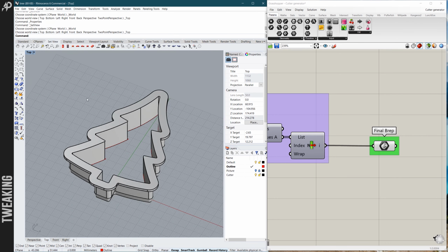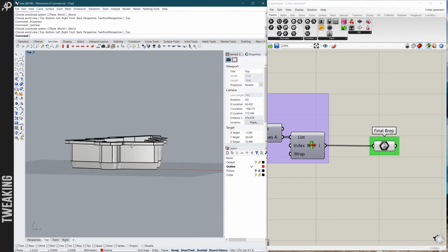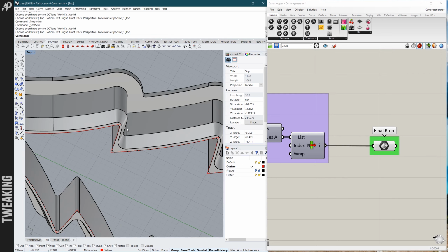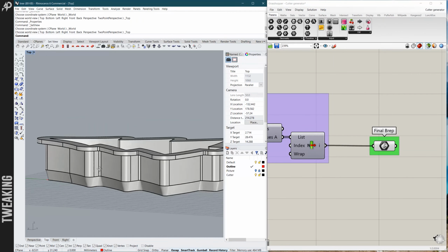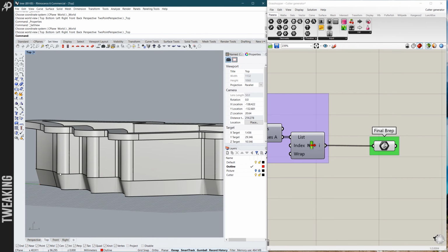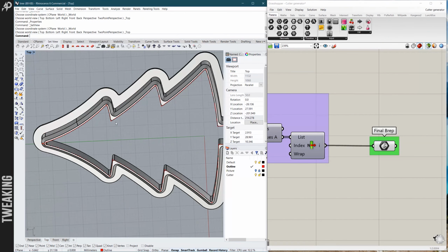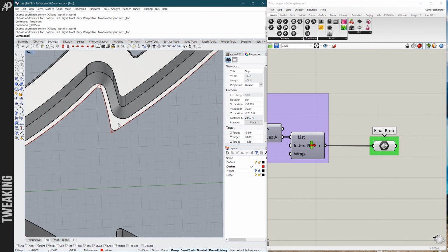So anyway, what is here to improve? It's quite obvious that I'm creating lower chamfer by sweeping triangular cross-section along the axis that consists of the outer outline. And that naturally means that in the inner corners there will be some deviations happening.